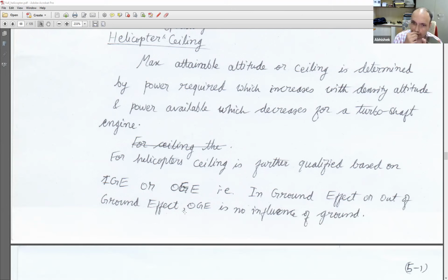With helicopters, to go at higher speeds with high weight, or even at lower speeds at higher thrust, my blades may be operating at very high angles of attack. First of all, they operate with a very high pitch angle. The peak to peak variation of the pitch angle, the sine wave amplitude, will be as high as 20-25 degrees. I don't know if I have my presentation handy. From my PhD defense, I could have shown you exactly how high they become.